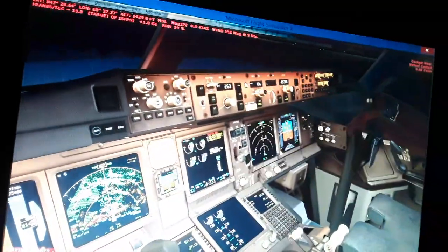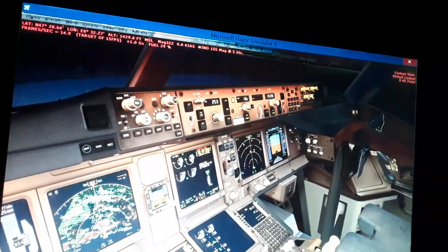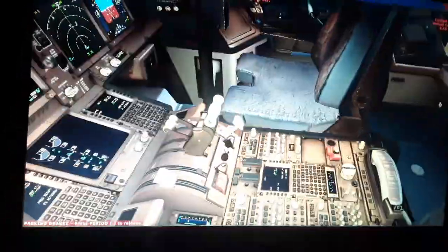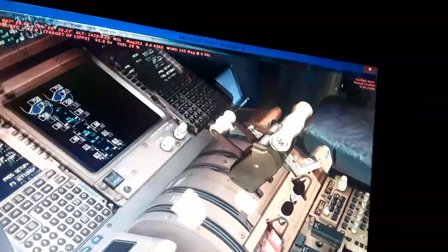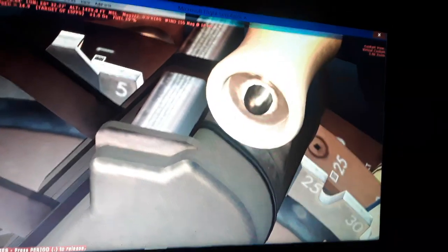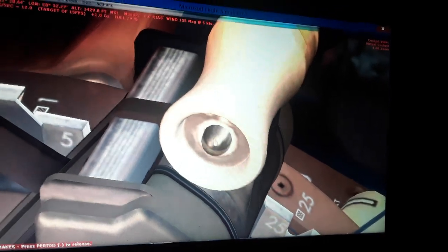So the auto throttle, when it engages, you engage the autopilot and the auto thrust, and the flight director commands over here. So this is the takeoff go-around. This is the auto throttle disconnect switch over here. You disconnect the automatic thrust and you take manual command over there.